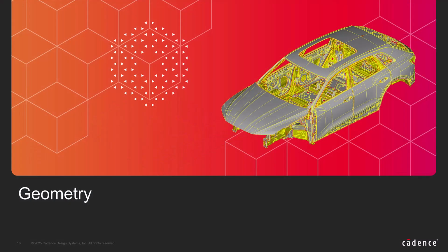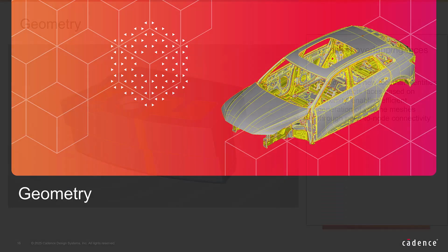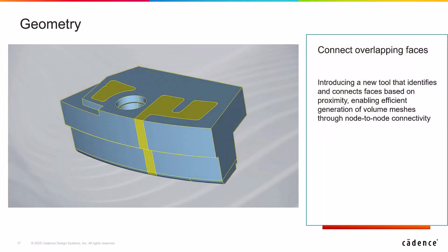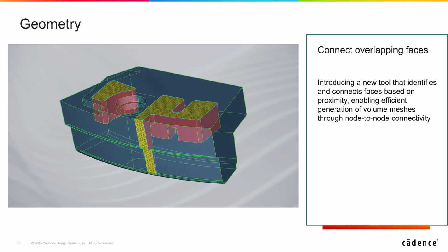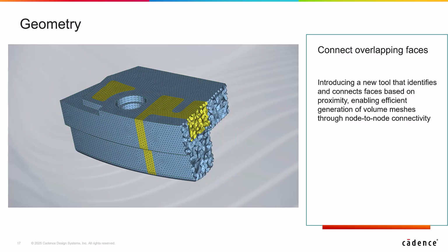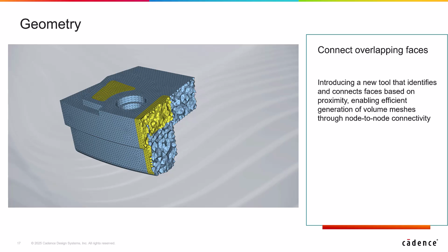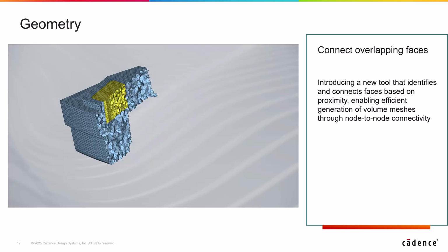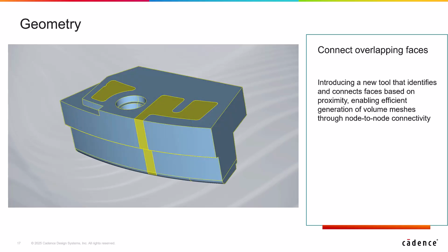Regarding geometry, we're introducing an innovative tool developed to enhance mesh generation workflows. It automatically identifies and connects faces based on spatial proximity. This significantly streamlines the process of generating volume meshes with node-to-node connectivity.